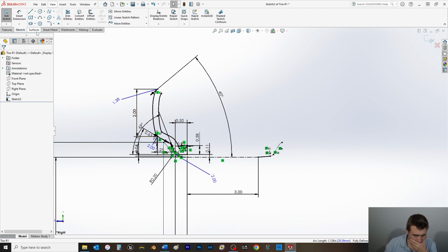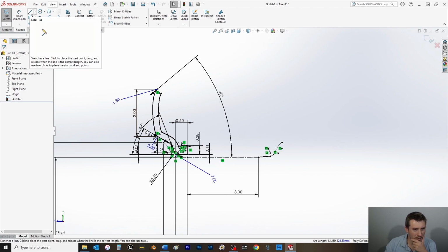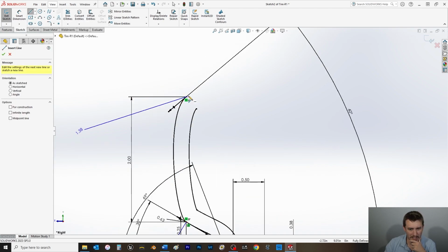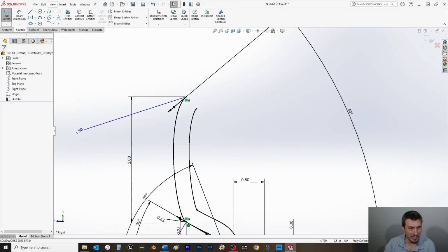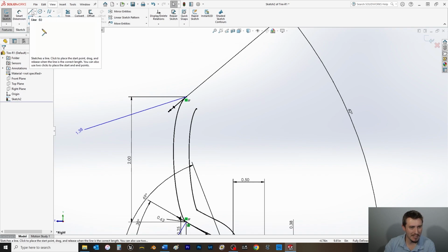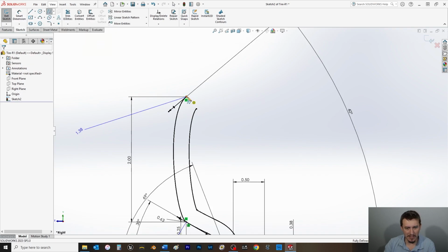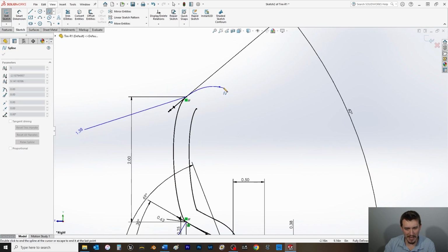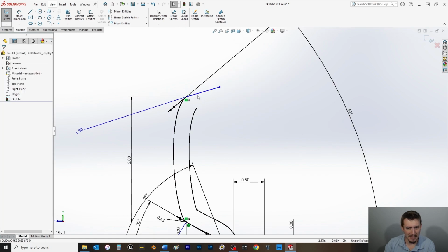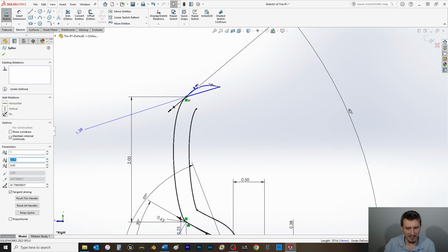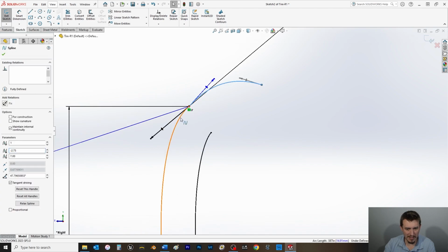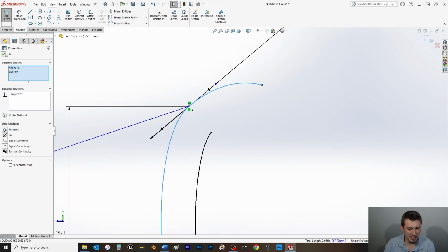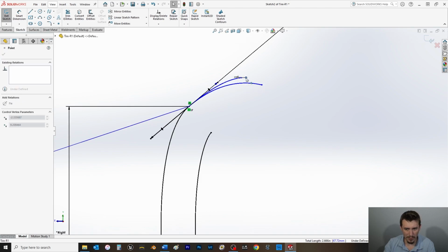And we'll go flat from here, or tangent. Let's see what tangent gives us. That would be like that. So we need yet one more spline for this, just to kind of level it out, because if we go tangent from flat, that's going to be a little messy. So this, let's get the handles out like such. Then we're going to take this part and do tangent. This is just going to be a small tweaked arc to give us something kind of flattened out.